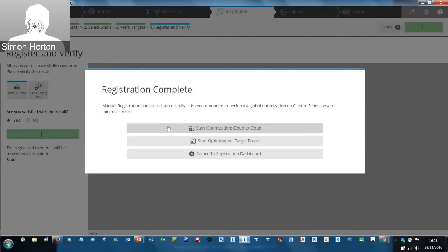The worry, or the problem, is sometimes, if you go for this option, when we've done our target-based registration, we've typically worked with a minimum of 3 spheres. If we then optimize it with cloud to cloud, that goes beyond and outside of those 3 spheres, and it starts to use everything else in and around. So it will pull the spheres apart sometimes. So typically stay with the option that you've used.